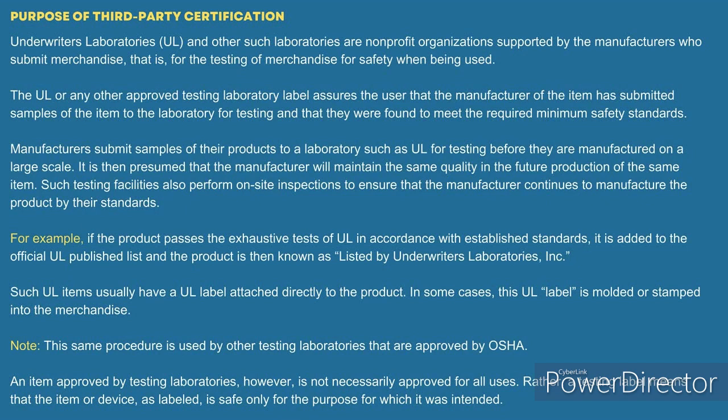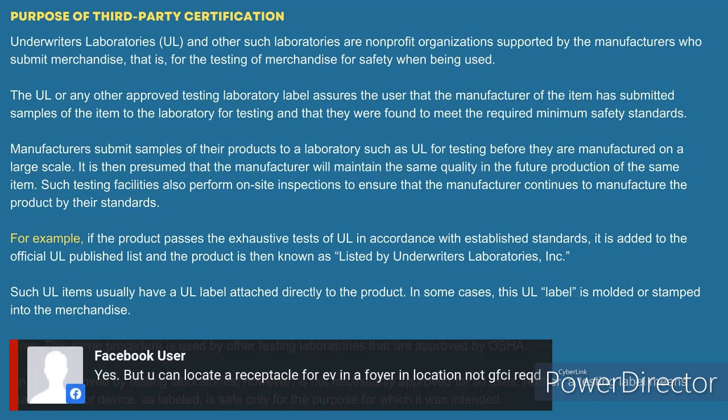So basically, you just have an ungrounded conductor and a grounded conductor, and then you use a GFCI in lieu of having a 3-wire connection. That's a really valid argument, Justin. Well, that's allowed by code. I mean, when you're getting into replacement of receptacles and you're providing GFCI protection because it's required in that location.